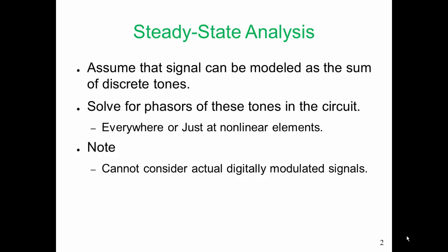But you know what? When we're in the lab, we do most of our measurements using discrete tones. We may apply a single sinusoid to a linear circuit and sweep that single sinusoid with frequency to get the linear response of the circuit, the linear steady-state response in the frequency domain. We also do two-tone testing in the lab. We can do the single-tone testing and the two-tone testing in simulation, either for a purely linear circuit or a circuit with nonlinear elements.